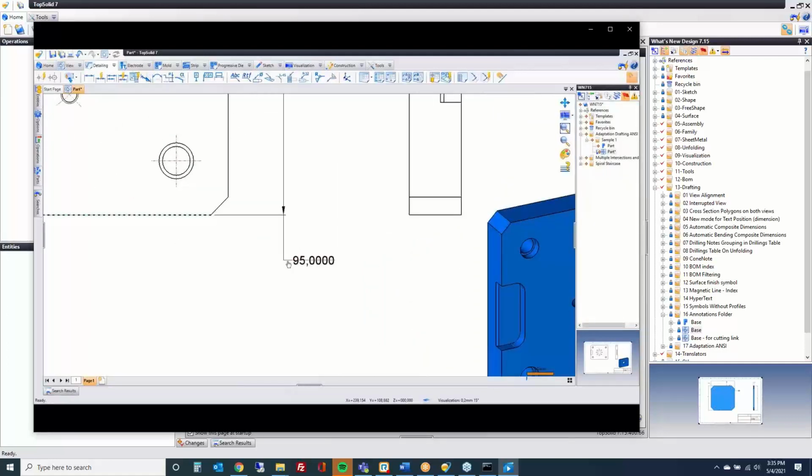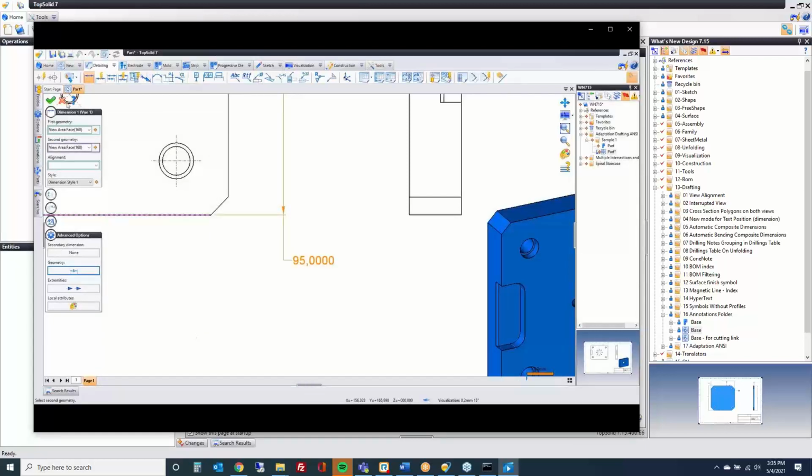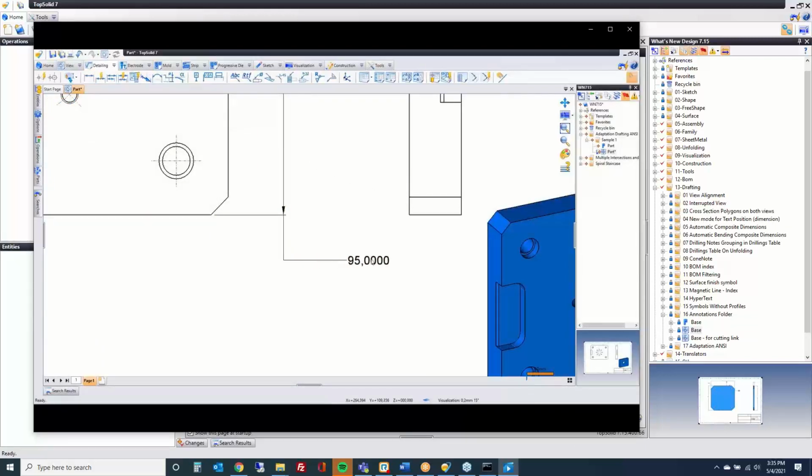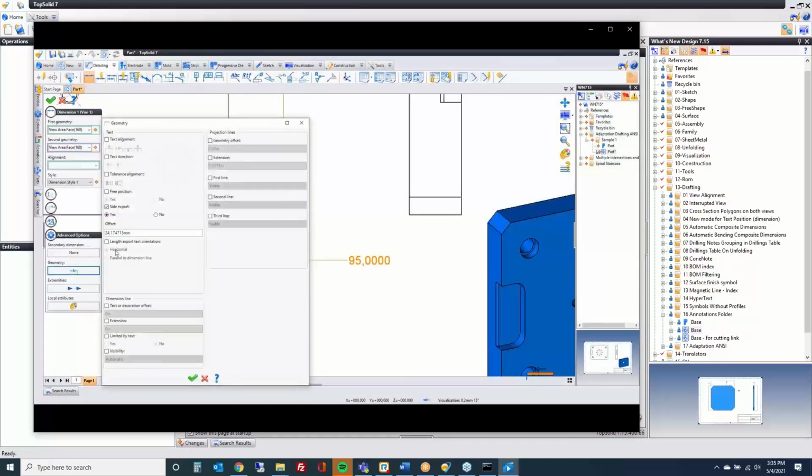So now we can pull it down. You can see the dimension shows up, offset. We can edit that. We can go to the geometry and you can play with the offset there. Once you have manually changed it once, then you can come in here and you can type whatever value you want or set it back to the standard.